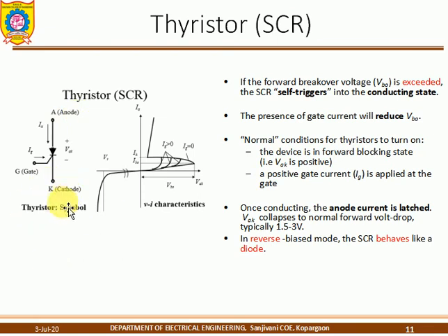Once you trigger the gate terminal, and the current is equivalent to the latching current, the thyristor will start to conduct. The minimum current required to turn on the SCR is called the latching current. When the current goes below the holding current, hold.